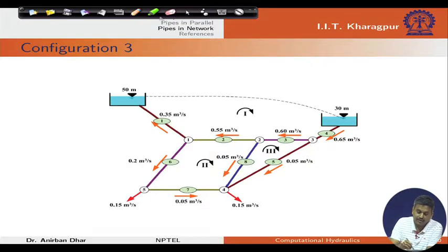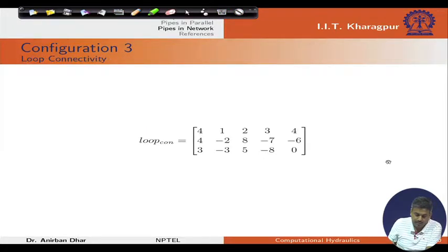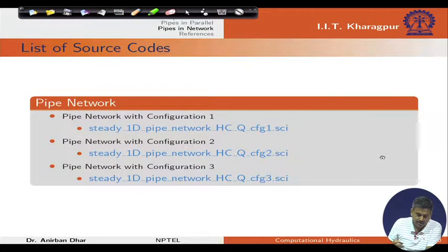So, this was having a positive value because positive Q for these 4, but finally when I have got the results, they are showing negative values. That means the flow is just opposite to the assumed direction. So, with this 3 you can change different values and get the desired value for a specific network.